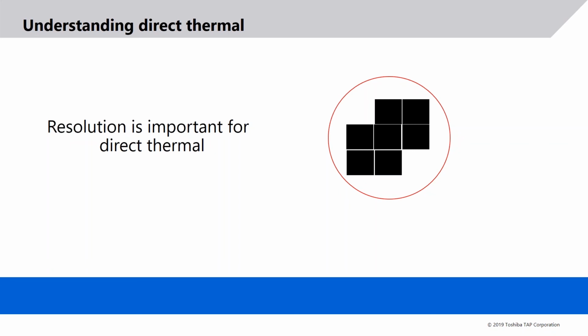So when you use direct thermal, it is literally just burning that specific spot to generate a black image. And so you'll find that between direct thermal and thermal transfer, direct thermal tends to have this sharper, blockier type of look, whereas thermal transfer tends to be a bit of a finer print. So we'll be looking at that as well.